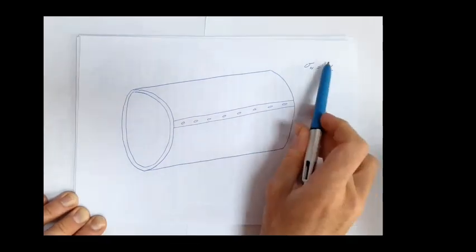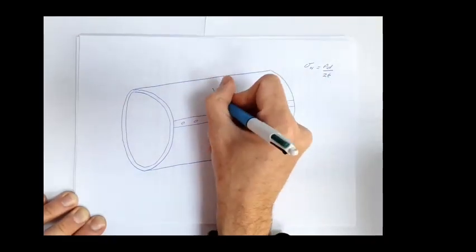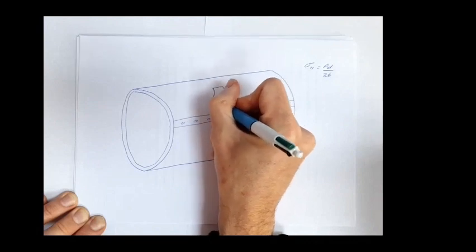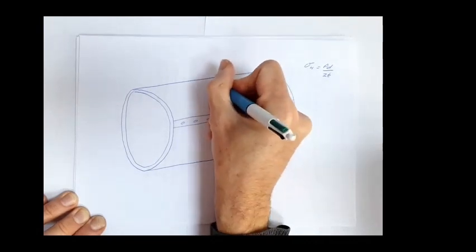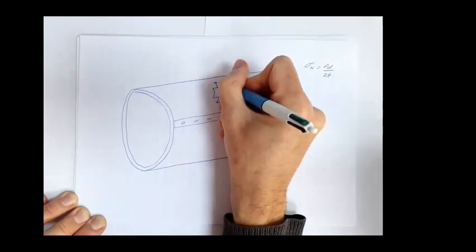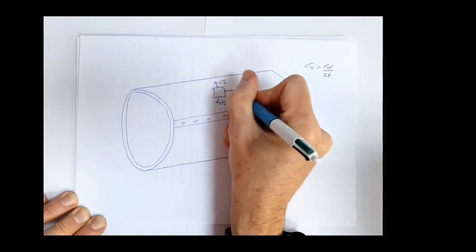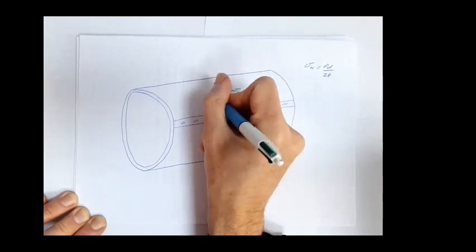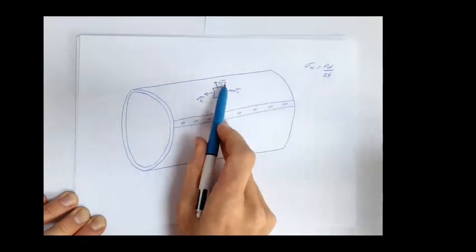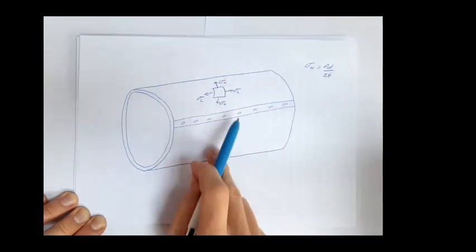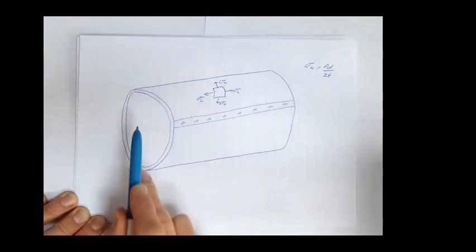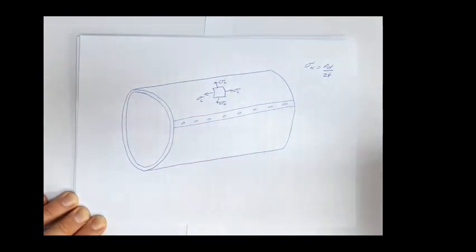However, those hoop stresses, remember, there's my piece of material, my hoop stresses are going in this direction, and my longitudinal stresses are going in this direction. Okay. So the hoop stresses are trying to stop the cylinder from expanding. The longitudinal stresses have been set up by the pressures on the end plates of our structure.